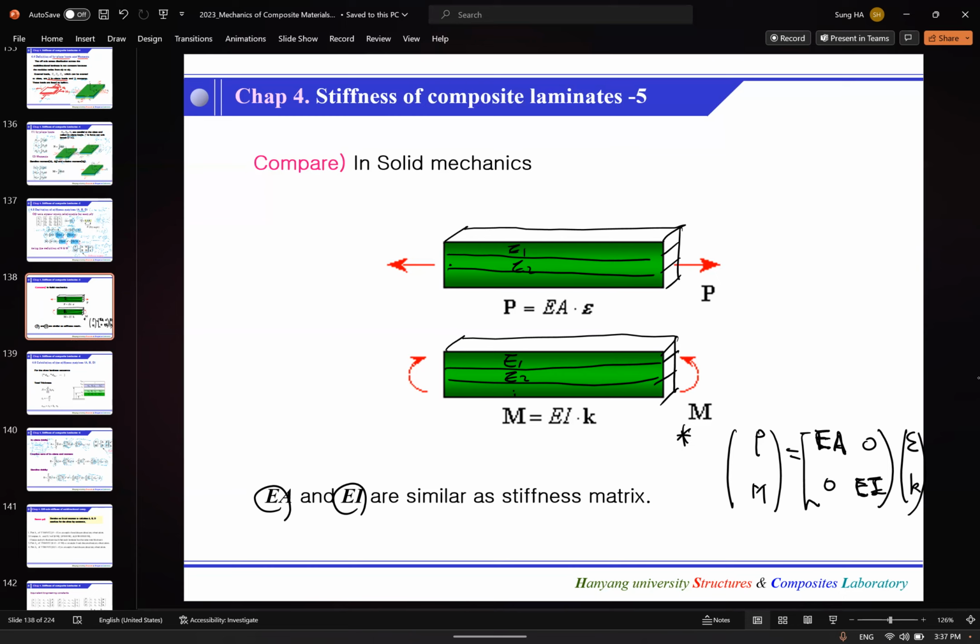We can have some equivalent material stiffness representing the stiffness and ply thickness information, and even further. So I'll just show the hat, I mean the bar, representing the stiffness. So the concept is that this term represents the material property information, and A means the information about each thickness. Okay, that is a very important concept. And bending stiffness is the same thing.